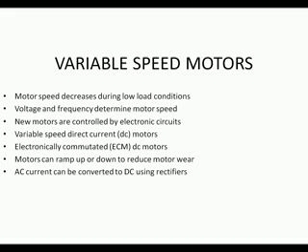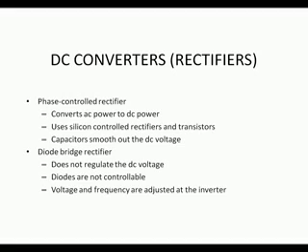Three-phase compressor motors are used in large commercial industrial applications. They normally have 3 motor terminals. No capacitors are required, and resistance across each winding is the same. These three-phase motors have very high starting torque. Some larger three-phase compressor motors operate as dual-voltage devices.